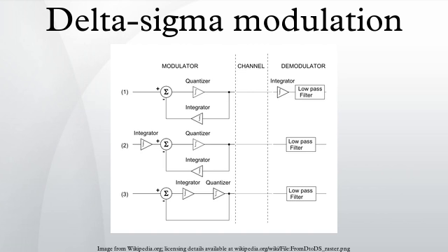Besides its noise-shaping function, it has 2 more attractive properties: simple to implement in hardware. Only common digital blocks such as accumulators, adders, and D flip-flops are required. Unconditionally stable. A very popular decimation structure is the sinc filter. For second-order modulators, the sinc3 filter is close to optimum. Quantization theory formulas: when a signal is quantized, the resulting signal approximately has the second-order statistics of a signal with independent additive white noise.